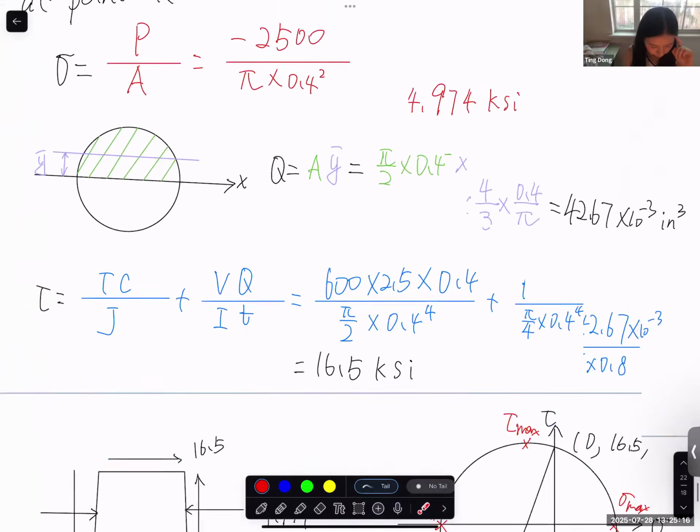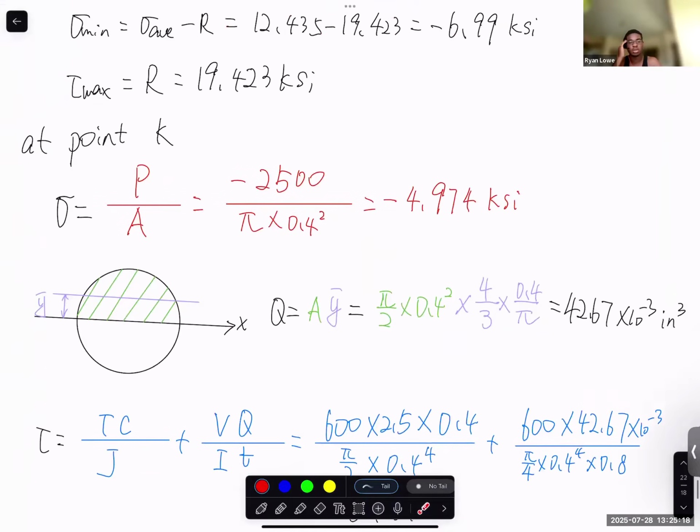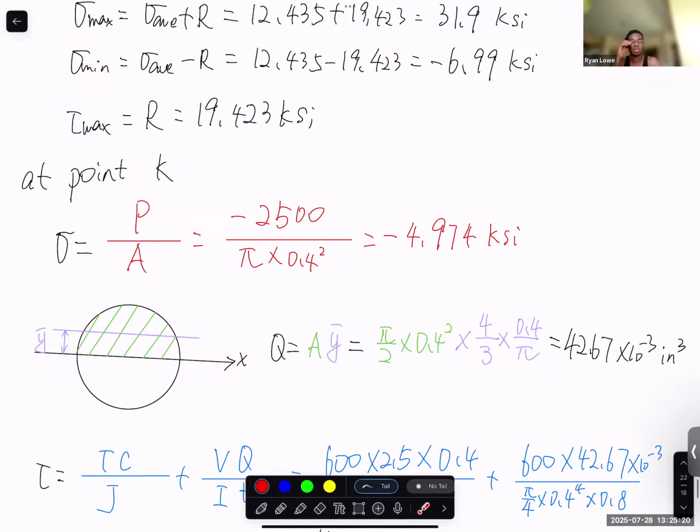Any question? What would the thickness be in this one? Here. Okay. Yeah, so let's say the force is applied in this direction, right? This is a transverse force, and you are trying to figure out how the shear stress changes in this direction, and of course it starts from 0 here and 0 here, and to see how it changes in between, use VQ over IT.